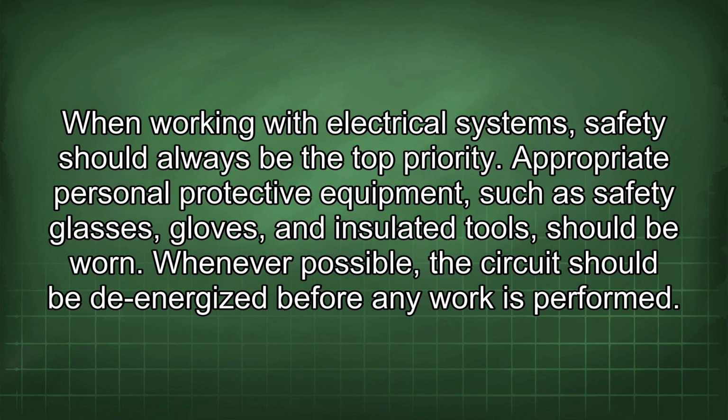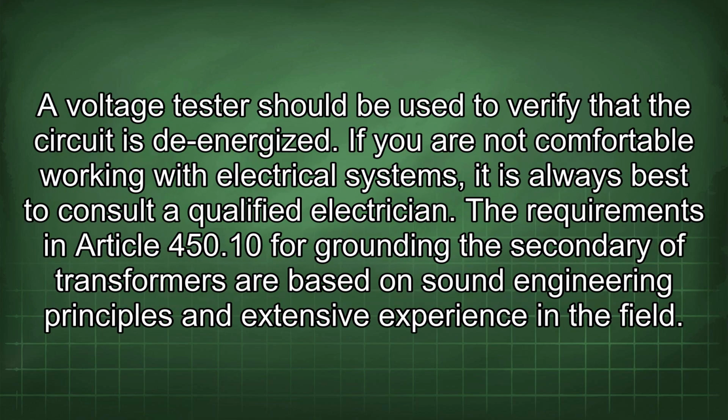When working with electrical systems, safety should always be the top priority. Appropriate personal protective equipment, such as safety glasses, gloves, and insulated tools, should be worn. Whenever possible, the circuit should be de-energized before any work is performed. A voltage tester should be used to verify that the circuit is de-energized. If you are not comfortable working with electrical systems, it is always best to consult a qualified electrician.